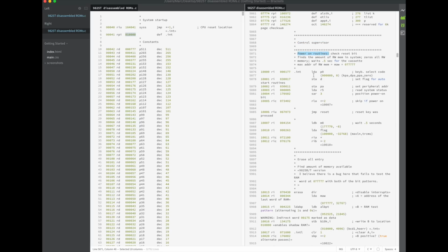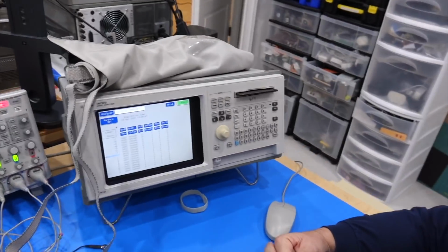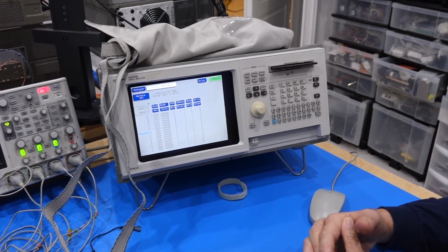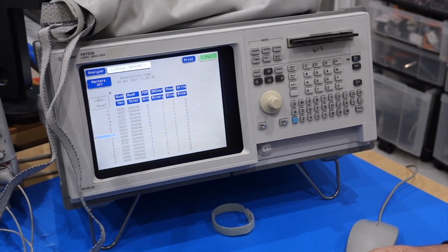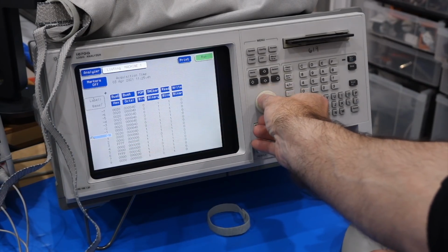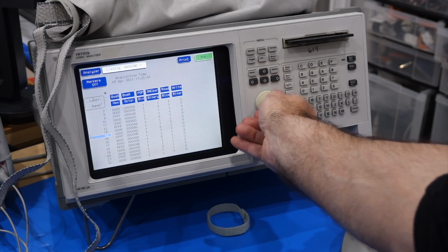So what we can tell from this is that on boot, it should read from address 040, the jump, then 041, the address where it should jump, then jump to 10,000 and start executing from there. Excellent. So the processor, we expect it to start at address 40, and then it should jump to 10,000. So 40, then it's reading where it has to jump, and it's not jumping. Right.